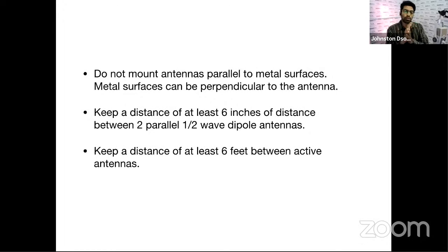Now this is the thing we spoke about. We have spoken about one small part of deployment. Let us talk about more things in deployment when you're deploying these systems. Never have antennas parallel to metal surfaces. Now, if this is a metal surface, my phone is like a small metal surface. You do not want to have the transmitter antenna parallel to it.